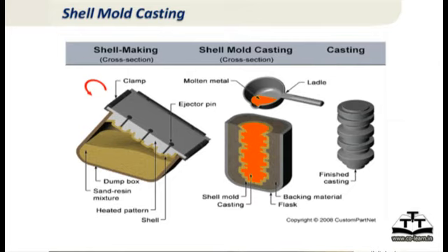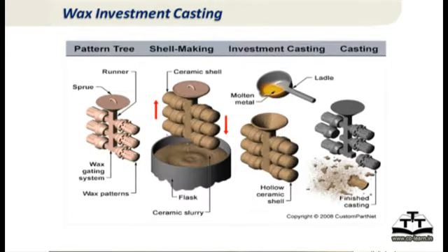That is a small thickness of material, so this is a much more efficient process in terms of usage of mold material. You also get much better dimensional tolerances and surface finish compared to green sand casting. Now going in this direction, the next sand based or expendable mold process is investment casting.